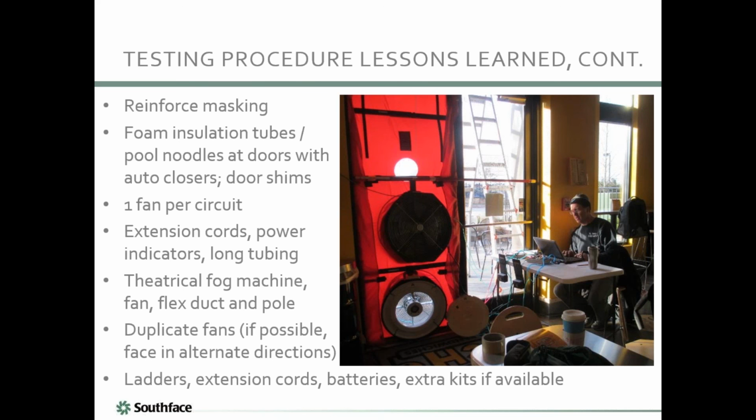There's some tricks you can try to work around that, but the best thing is by far to get everybody on its own breaker. One of the tricks, if you've got 2 outlets in a room and you want to know if they're on the same circuit, is to get one of those pretty inexpensive little things like a watt saver or a kilowatt that you normally plug in the wall and then plug appliances into, and it tells you what the watt draw is. So you plug it in the wall and you look at the voltage on it, and then you go to your other outlet and you plug in a blower door. You turn it on full, and you watch, and if the voltage drops more than a volt, then they're probably on the same circuit. And if it more or less stays the same, then it's probably on a different circuit. So that's a good little trick.